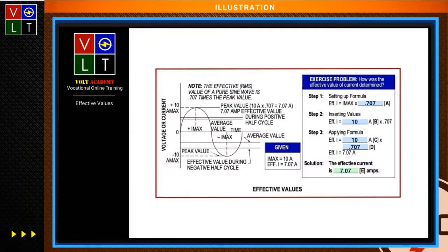Sure. And when you look at that effective value of that alternating current, when we're calculating, it's by comparing it with what? Direct current, actually. Yep. Okay. So when I look at this comparison, it's going to be based on the amount of heat produced by current under the same conditions of use. And that heat that's produced by that current is always proportional to what? The square of the current. Right. Okay.